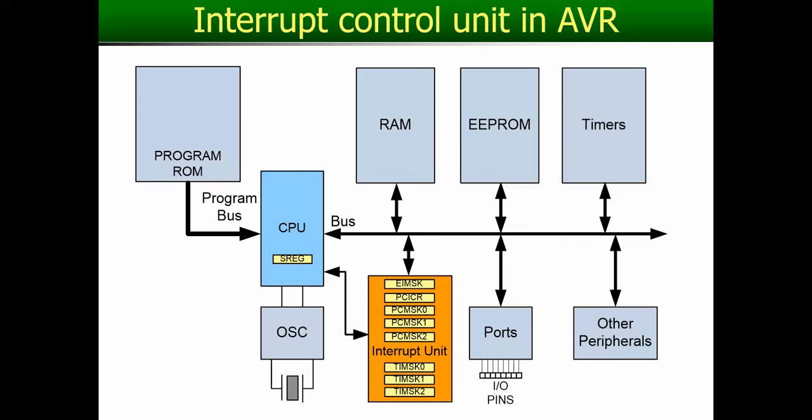So this highlights the interrupt unit that deals with configuring the interrupts, disabling the interrupts, enabling the interrupts, controlling the interrupts. Configuring, that's the most important term, configure an interrupt. For example, I want this interrupt to happen, but I don't want that interrupt to happen. I will entertain the timer interrupt, but let's say I will not entertain the external interrupt.